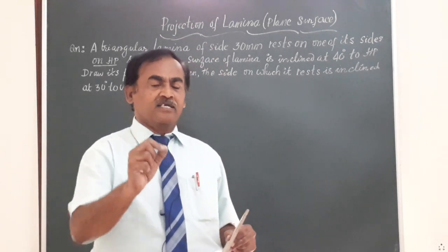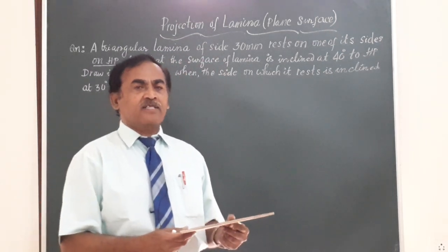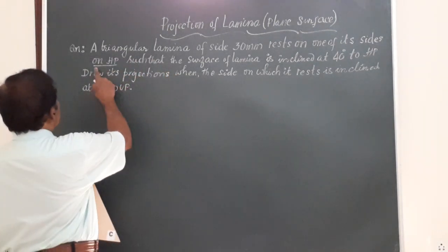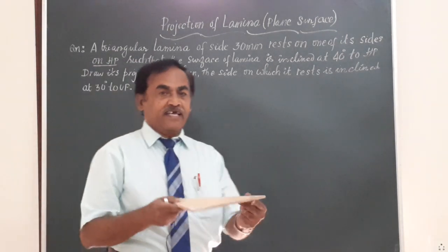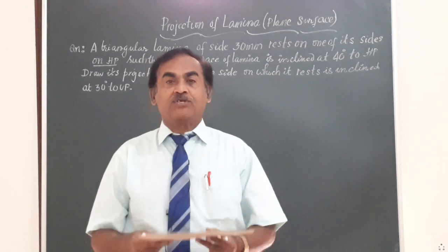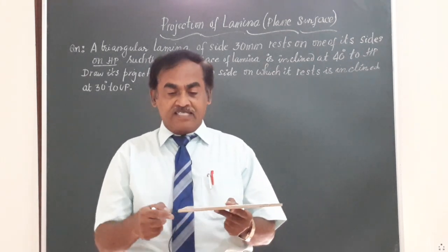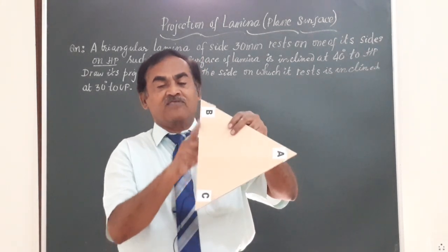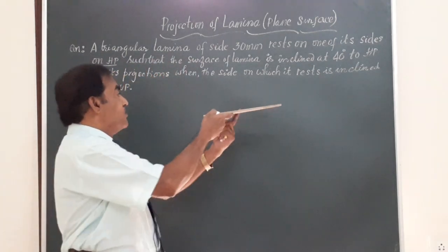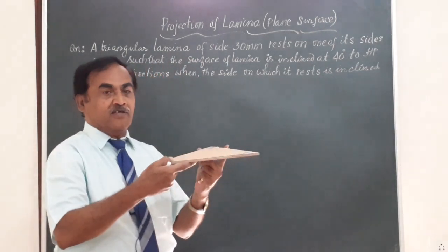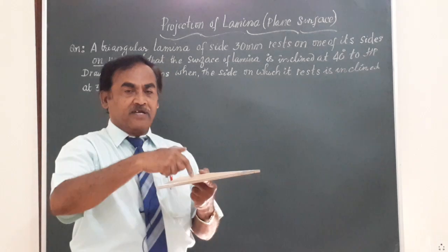So I will just remind you again, friends, whenever you find a phrase like rests on HP, simply place that lamina on HP or on the ground such that one of the sides of that lamina is perpendicular to this wall VP. Obtain its top and front view.